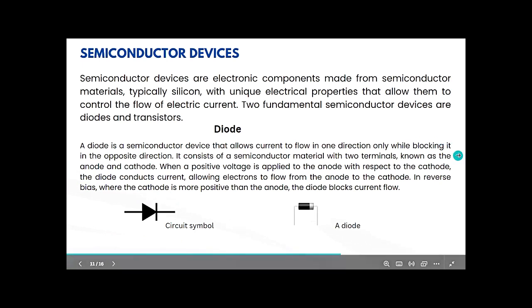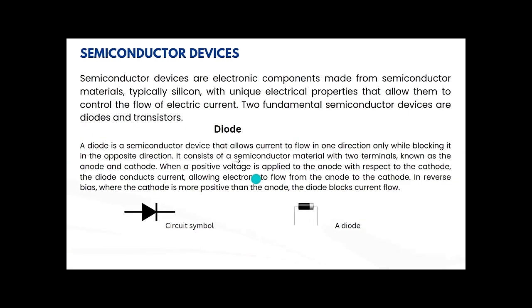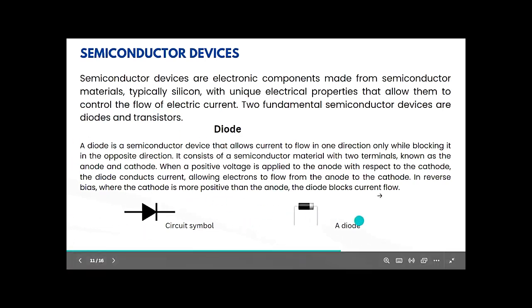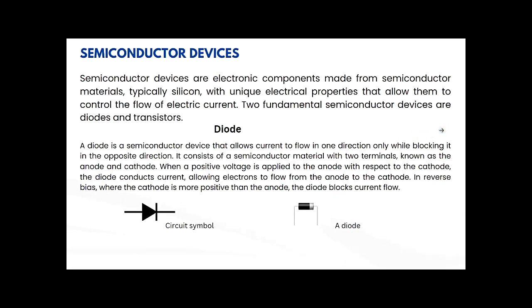So diode, there are different types of diode, like p-n junction diodes, Zener diodes, photodiodes, Schottky diodes, and other types of diodes like that. And each of these diodes has their applications, like p-n junction diodes are being used to allow current to flow in only one direction, and Zener diodes can be used for voltage regulation. And Zener diodes are connected in reverse bias and not forward bias.